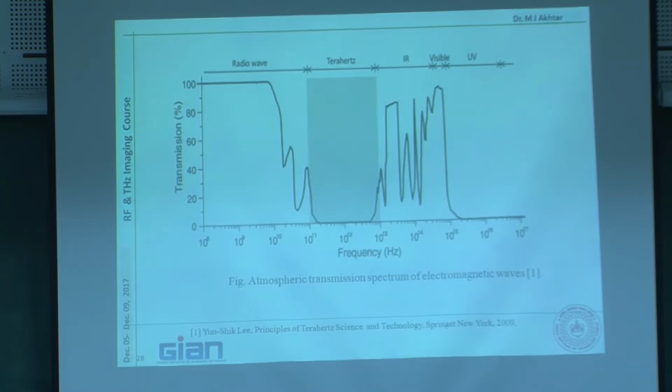This is just to show the problem. If you look at the atmospheric attenuation, you see that it's really very bad in the terahertz range, almost like there is no transmission. That is why this is not really a good choice for a normal ground station, where the density is high and you have high losses. And you should understand that before you start working on terahertz.